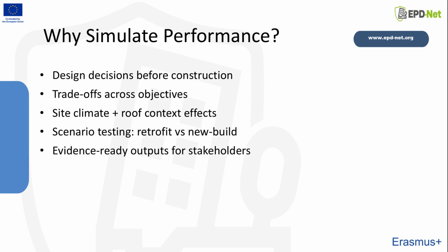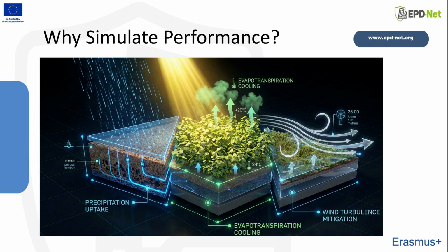In practice, the most useful outputs are comparative: baseline versus green roof, thin versus thick substrate, irrigated versus non-irrigated, and current climate versus future climate scenarios. A good simulation question is always phrased as a comparison. Compared to what, under which climate, and over what time window?